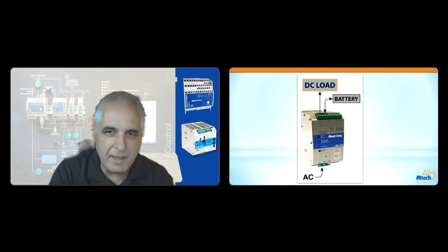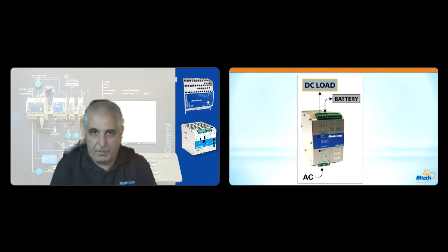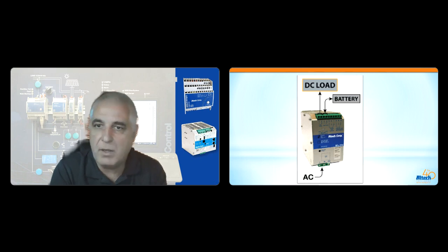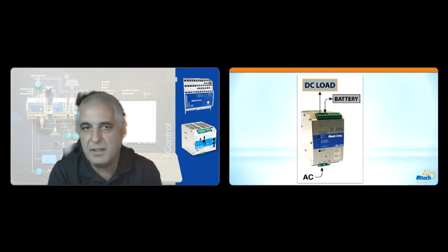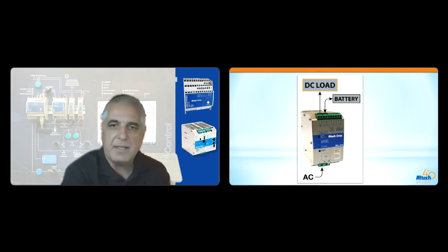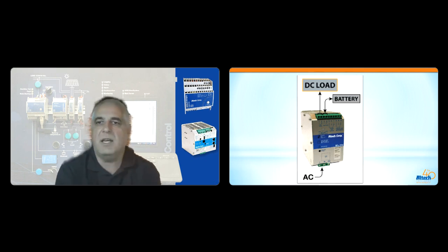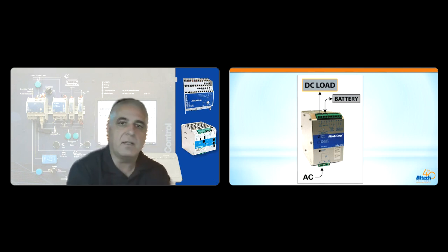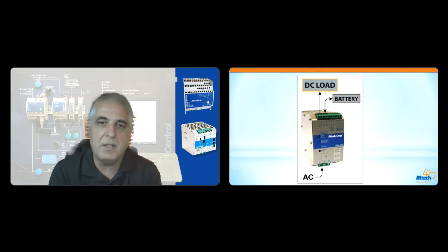Some of these capabilities include user-selectable charging curves that facilitate compatibility with virtually all battery types, including lead-acid, sealed lead-acid, gel, nickel-cadmium, and lithium-ion batteries. Automatic multi-stage charging operations with real-time diagnostics enable the fast recharge and recovery of a deeply discharged battery, which adds real value and reliability to a DC UPS system.